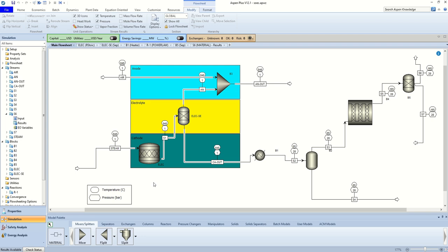So now coming back to the solid oxide electrolyzer, the coding has been done. This is the stack part, and here goes the cathode where the majority of hydrogen is produced. This side is the anode. Now the BOP is a little different than the alkaline electrolyzer one, because here the temperatures are 848 degrees Celsius and 1 bar pressure, which is different from the alkaline one. The temperature was 75. So now we need to cool back the water, or the steam rather in this case, so that we can separate it from hydrogen and get pure hydrogen.